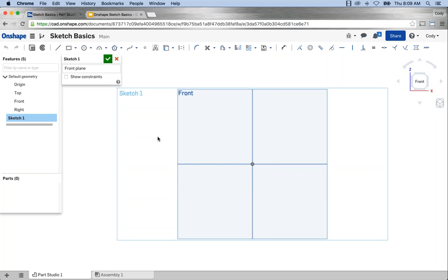And so that often means that starting a sketch is 3 steps. I select the plane or face, I select sketch, and then I view normal to sketch plane. That's pretty standard for almost every sketch that you're going to do.